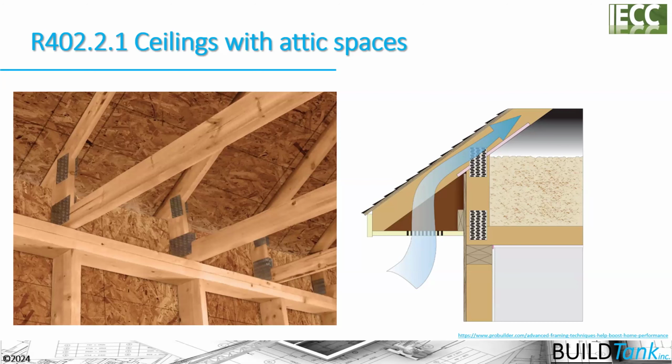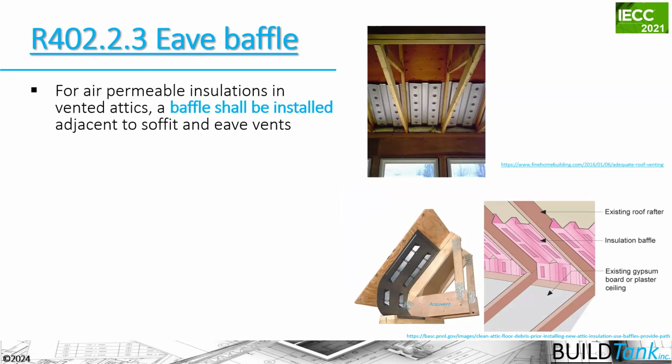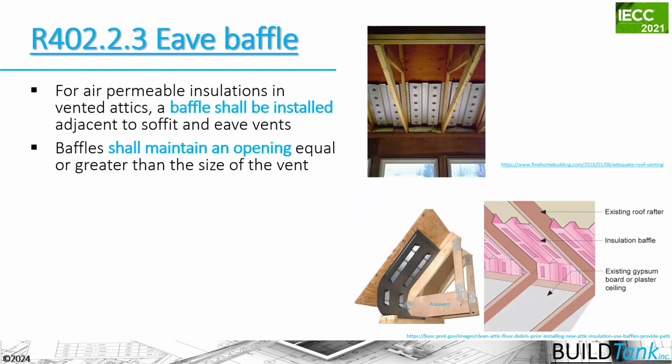Also, if you're going to put in attic eave baffles for a ventilated attic, you'll need some space for that as well. So you might need a 10 to 15 inch heel truss to get that. And with an R49, you're potentially going to need an even more substantial one.